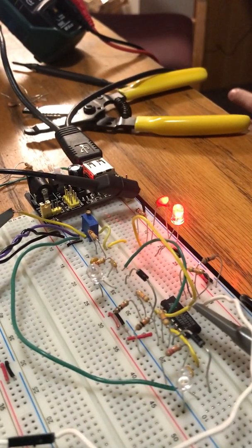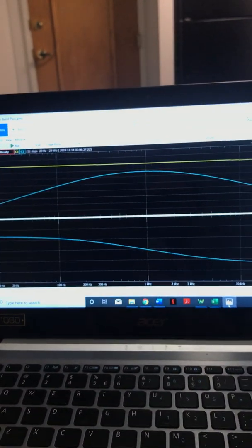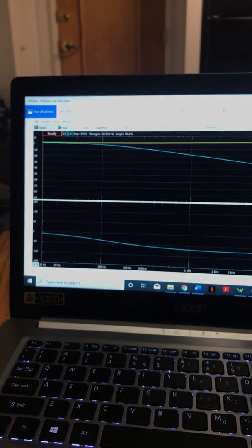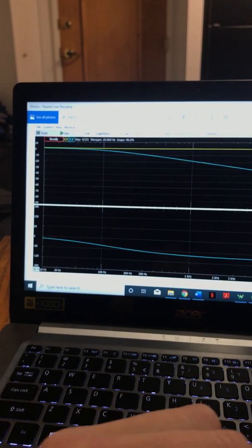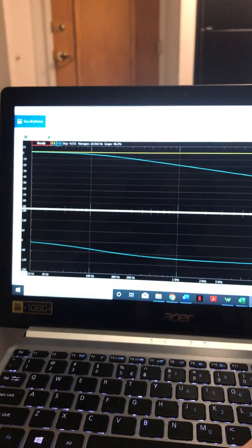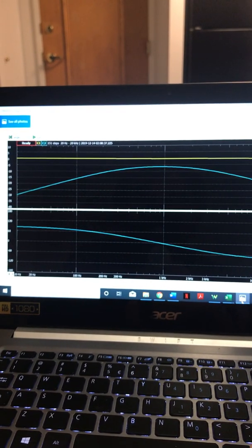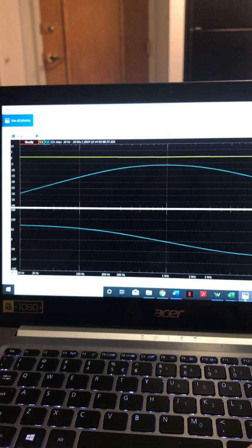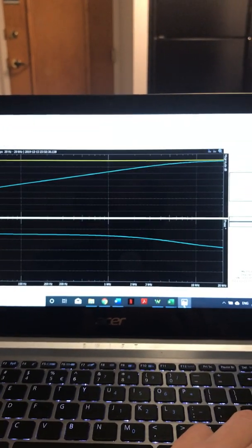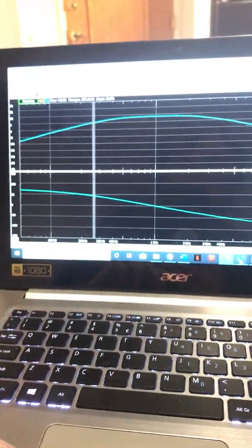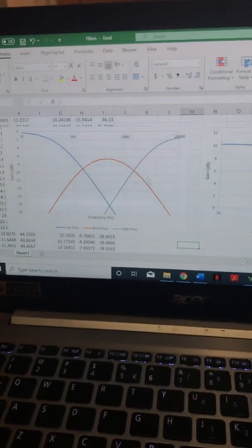And then we have a few graphs just to show a few images. Starting with the low pass, this is the low pass without the op amp, with no gain, so with no active components. So we start at a 0 gain and then go down from there as the frequency increases. This is the passive band pass, which is the same thing except the gain is just lower. And this is the passive high pass.